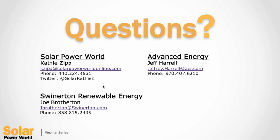This next one will actually be for Jeff as well. This person is wondering if you can share some experience about challenges faced with utilities and interconnection, maybe just briefly. Yeah, some of the brief examples you could look at are in distribution-connected applications. There may be a no backfeed interconnect requirement for a large commercial site, and in those cases, we partnered with other key industry offerings to develop controls and closed-loop systems to prevent active power backfeed onto the network.